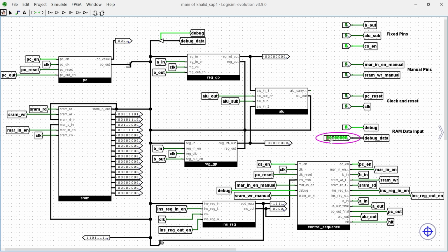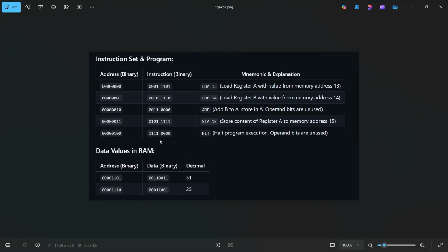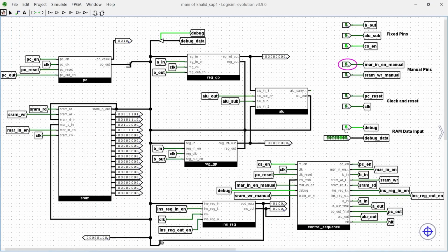So we have to do this for memory address 4. For memory address 4, we're gonna use 0100. So we have to memory enable, give a clock pulse. So this memory address has been chosen. Now we're gonna give the value. The value is, from left, 4 1. Okay, from left 1 2 3 4. We have to choose the write pin and give a clock pulse. So the value has been stored right here.